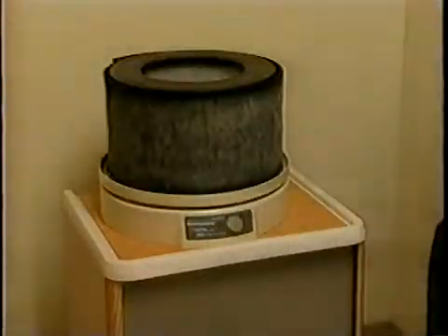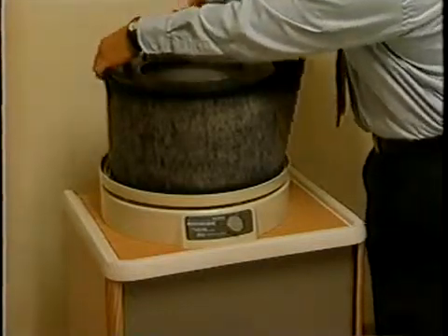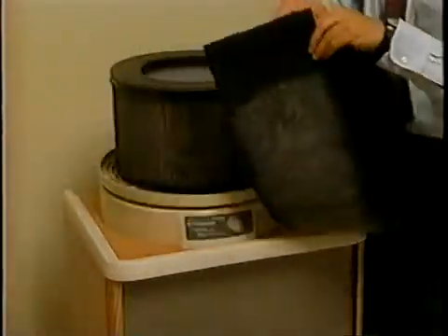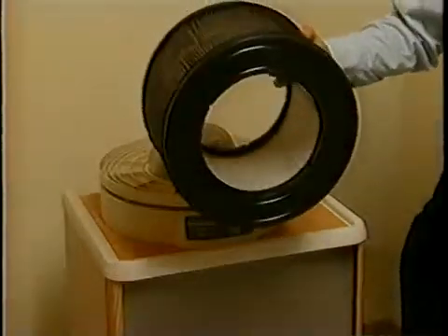HEPA filter units require very little maintenance. You should check the manual that comes with the unit, but in general, the pre-filters should be changed every 6 months, and the final HEPA filters should be changed every 1 or 2 years. Make sure that you change the filters and dispose of them in accordance with local requirements. In some areas, you may be required to wear respirators when changing the filters, and also to treat the discarded filters as medical waste. That's it for isolation room ventilation. Let's move on to negative pressure.